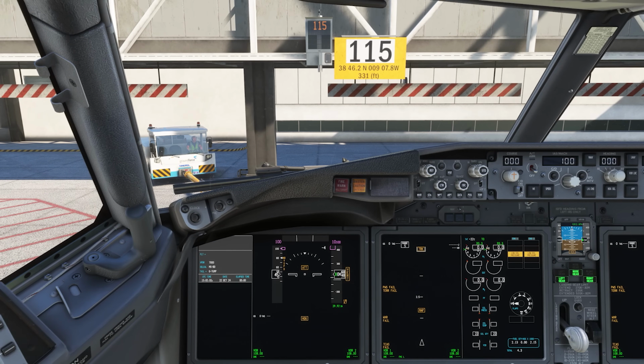And the EEC, electronic engine controls, are very similar as well. They have some additional features to allow for potential issues with the engine. They have something called TCMA and EOS. EOS is electronic overspeed, which prevents the N1 and N2 rotors from overspeeding and shuts down the engine as well. There's something called TCMA, which is thrust control malfunction accommodation. That detects uncontrolled thrust events or high thrust events on the ground, and it'll also shut down the engine if that occurs.